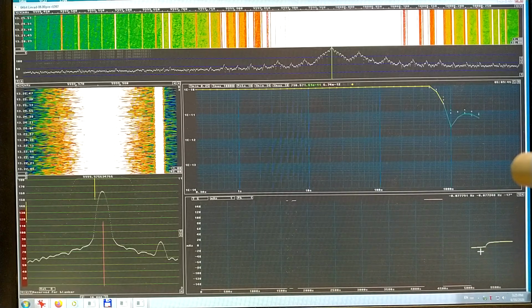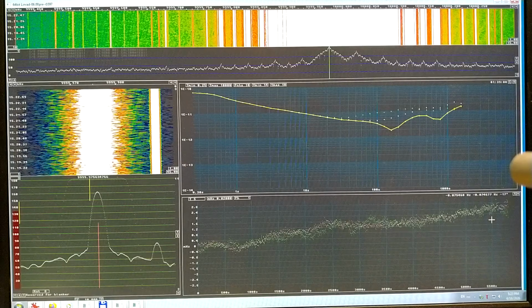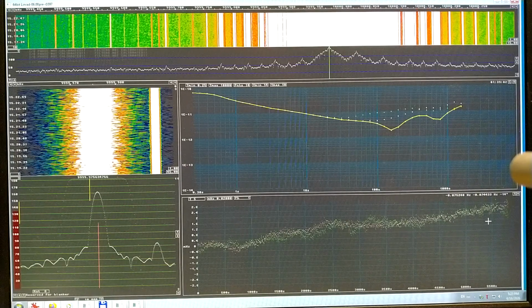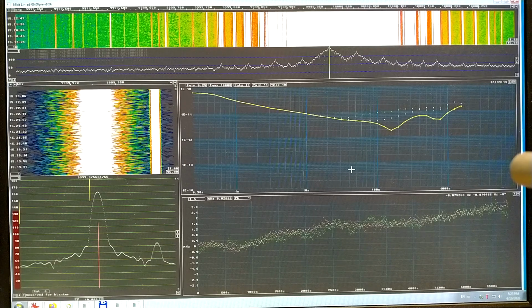And you see it has been about 500 seconds before I reach this fairly stable. I clear the screen and restart. It takes a long time for the rubidium source to become stable. This is 1.5 hours and the frequency drift is 2 millihertz. And that affects, of course, the Allan deviation graph.